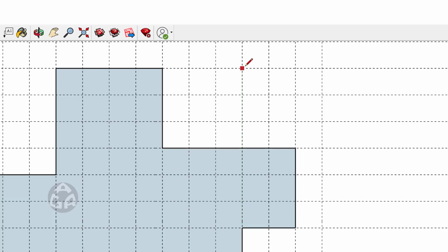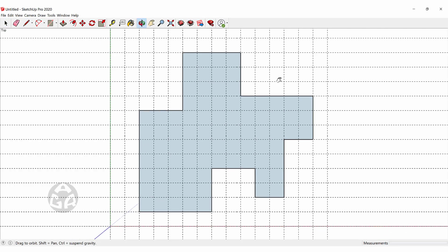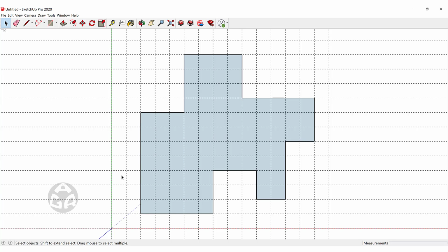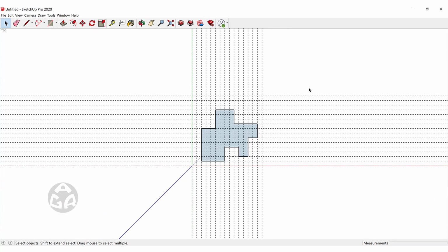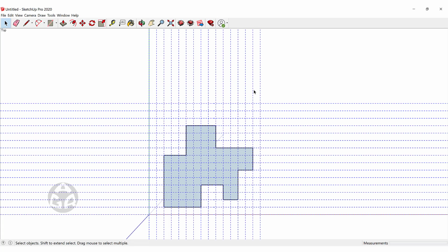You can see that when I activate the line, you can see a cross sign over here, and it says the intersection of these two guidelines. So I can just click and then click to create whichever plan shape I want. And then later on, I can just select all these lines, and then right click and click on make group to make all of them into a group.